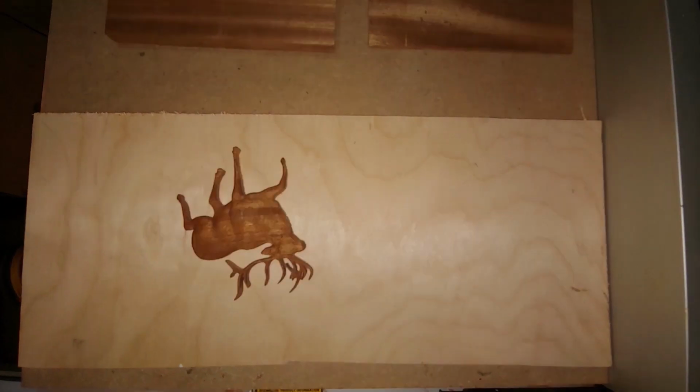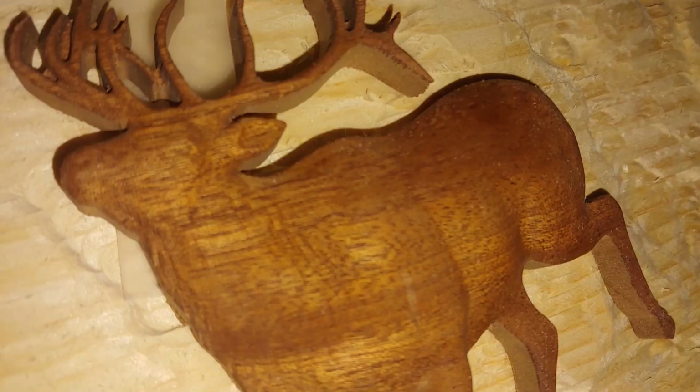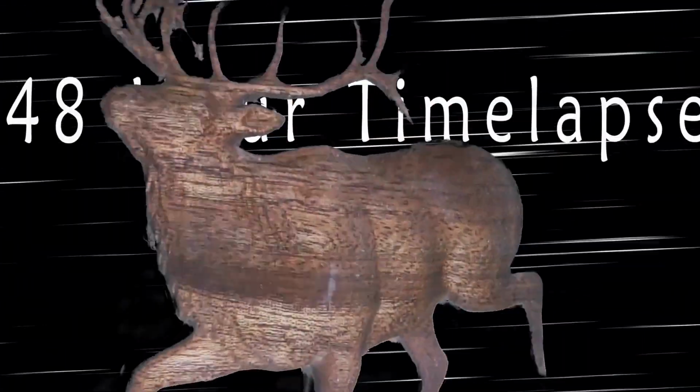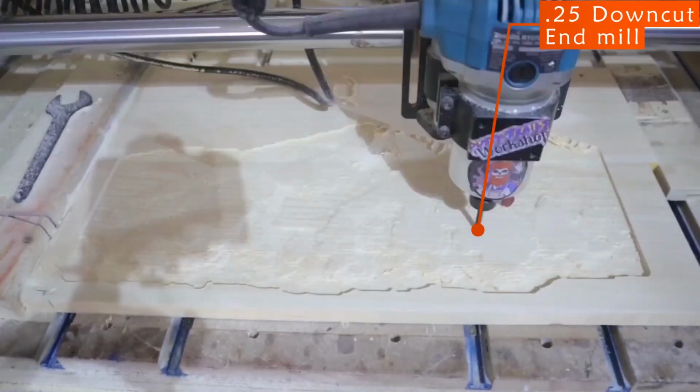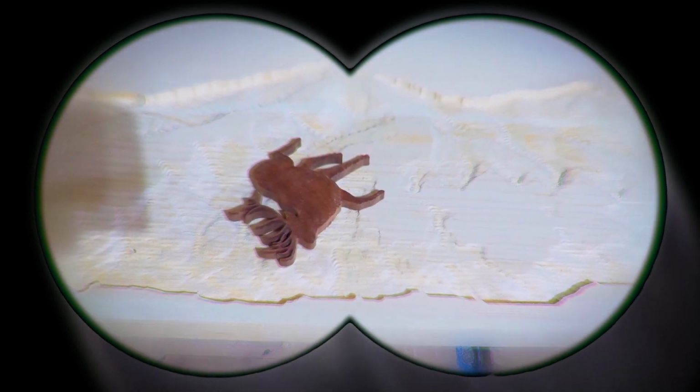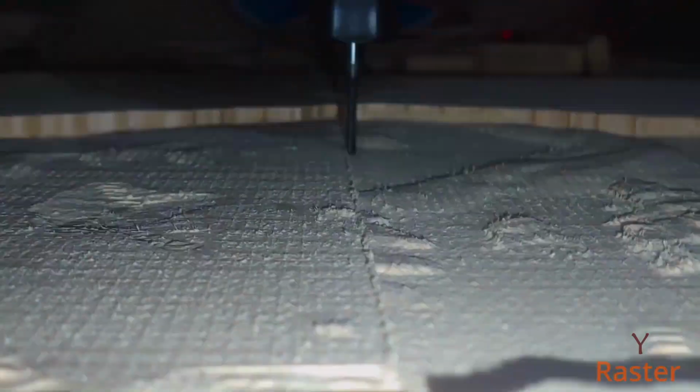Moving into the 48-hour time lapse of this mountain carve, it was a series of X and also the Y rasters for that 3D roughing toolpath. First with a 1/4 inch end mill, and then coming back over with an 1/8 inch end mill for that second raster. The second 3D roughing toolpath was also done with an ever so slight offset just to keep the jagged lines for those two subjects, thinking that mountains and trees in my vision are meant to look rough and not meant to look clean and smooth.